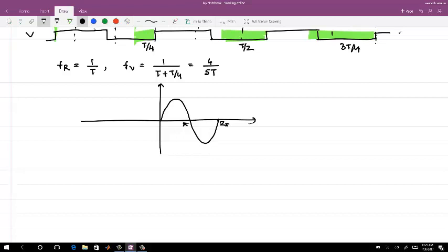Then we had, let me plot another. We have another phase error detector which was having a gain like this. You have seen this one, right? And this one was an XOR phase error detector. Then you have the two-state phase error detector which was like this. And then you have a three-state phase error detector which was like this. These are the characteristics of VPD versus phase error.